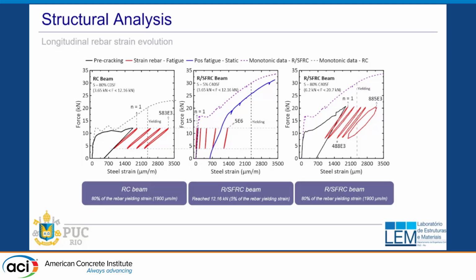If you go with steel fiber reinforced concrete and use that same level of the stress that was used for the FR1 value of the sample, we go to this same level of stress and we run our fatigue tests. Now we go 5E6, 5 million cycles, actually without much loss of stiffness, because with the rebar, you don't even get the rebar to go to any kind of yielding or accumulation of yielding. That's what's so important about using steel fibers that I've been pushing so much,